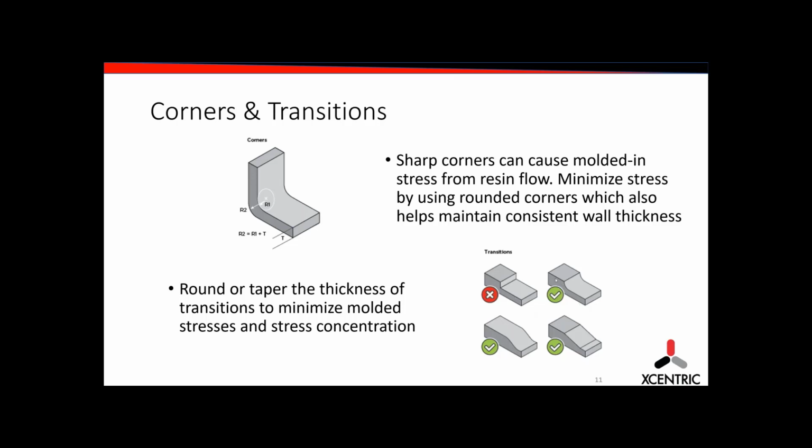There are ways around that. You can ramp it, or put a soft edge like a rad that'll allow the material to hit it and just keep flowing instead of smacking into that hard wall. And there are a couple other variations of that just to help with the material flow.